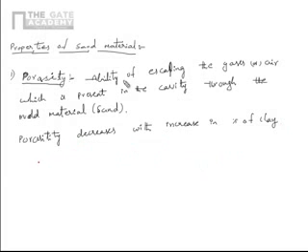Porosity decreases with increase in percentage of clay. Porosity also decreases with increase of ramming force. Why do we need to do ramming?